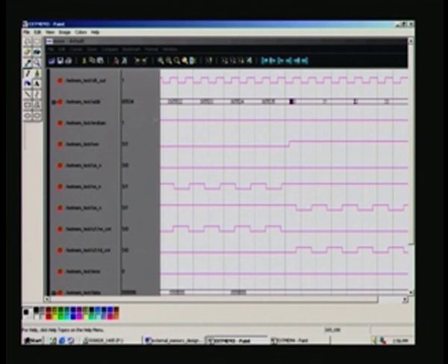So, this is the fag end of the test. It is 65532 and then 65535, then it rolls over to 0 here, 1 2 3 and so on. This is the address here, and now let us watch what is happening to this RWN control. It is all along low, that is what we started with. We started writing for every location up to 65535 the data, that is 555, which is at the bottom.